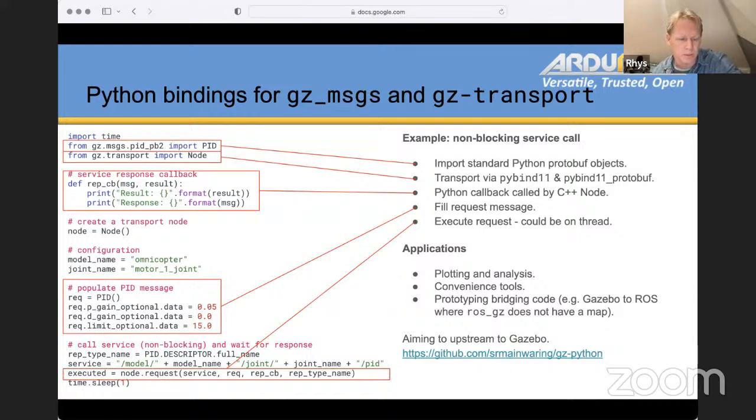So here's an example where all the controllers, and I mentioned earlier that these position controllers have PID gains, having to tune those, and you generally do need to tune each one within a simulation. It's very time consuming if you have to go back and edit the XML, restart your simulation, and relaunch it every time. So you can write a service on the joint itself, which will respond to an input message.